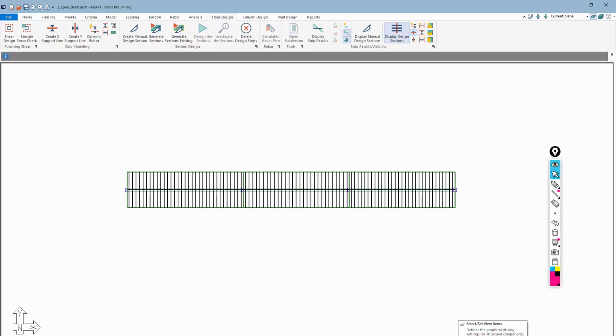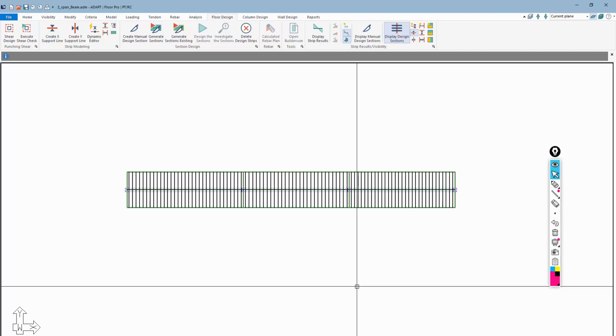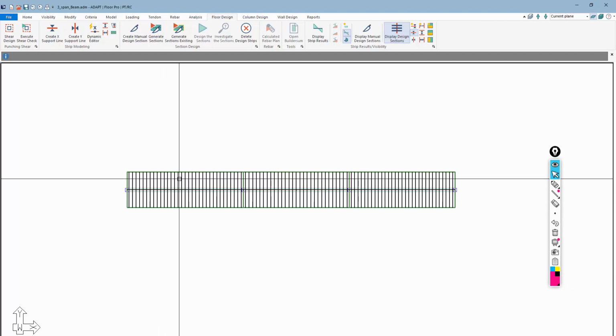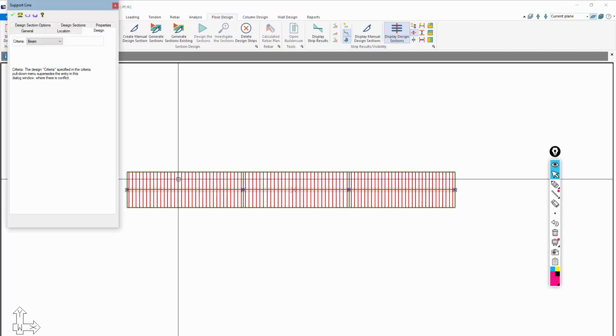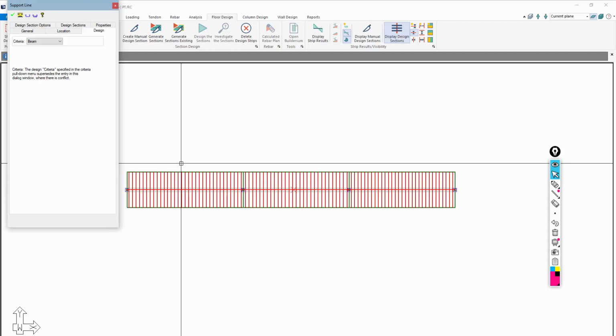The first thing we're going to do, just for the sake of showing how to model the tendons, and also maybe a starting point, will be to determine what level of post-tensioning we need, the number of strands we need just to meet pre-compression in the beam. So let's assume our target pre-compression is 150 psi. It's about 0.85 to 0.9 MPa if we were converting it to SI equivalent.